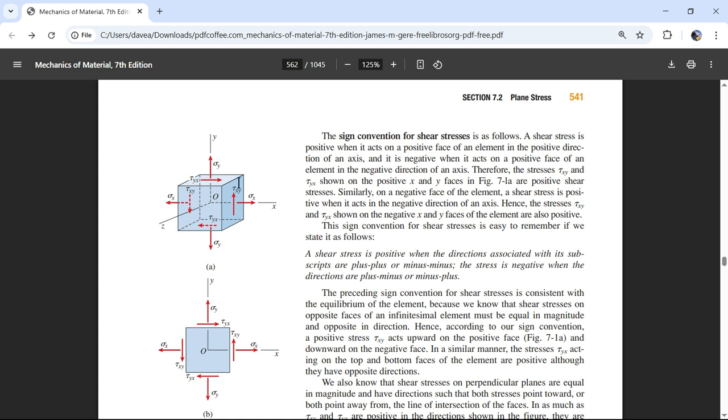So if I pull up on this face and do the opposite on this other diagonal, it's literally the same as tensioning the diagonals. That shows you that you have a normal pressure that's trying to tension these diagonals. And when we tension these diagonals, this box wants to collapse in. So this length decreases, and that would be the same as putting an inward force this way and that way.